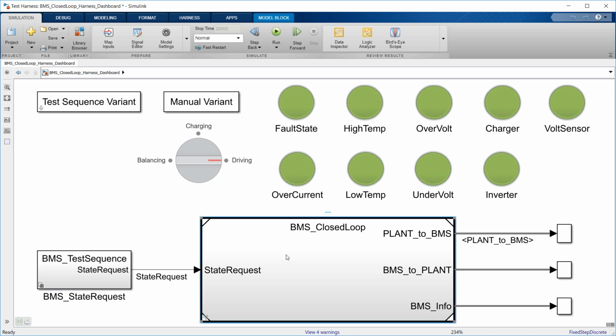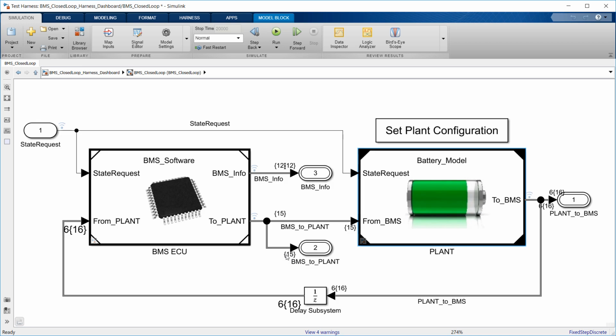The system itself comprises a model reference representing the BMS ECU with its various monitoring and control algorithms connected to a block with the representation of the battery pack and associated circuitry and peripherals. The battery pack is either a small 6-cell series or a larger 16-module pack, each module comprising a 6-cell series string. We call these architectures 6S1P and 96S1P packs, respectively.